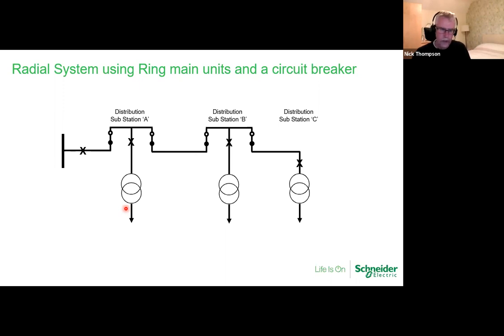And the transformer feeders are cable connected, so they're going to be radials. But in this instance, I'm showing 3 substations. Now, I have come across this kind of network in a customer's application, and it's because of the site construction, where it dictated they could only use radials with numerous substations on those radials, and they accepted the operational limitations that you have with this kind of network, which if we introduce a fault now on our network